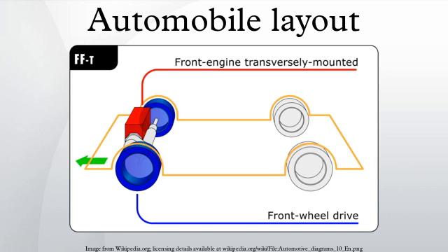Front-wheel drive cars, with a front-weight bias, tend to understeer at the limit which, according to Saab engineer Gunnar Larsson, is easier since it makes instinct correct in avoiding terminal oversteer, and less prone to result in fishtailing or a spin. According to a sales brochure for the 1989 Lotus Elan, the ride and handling engineers at Lotus found